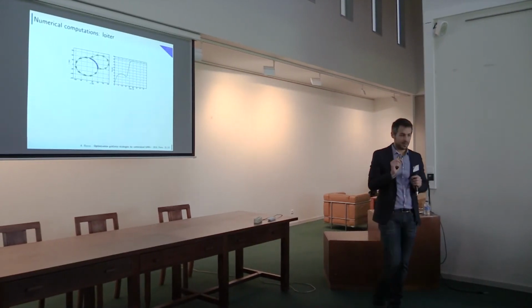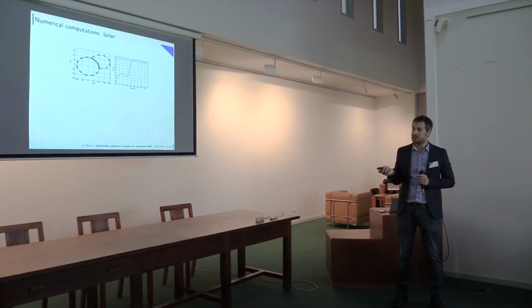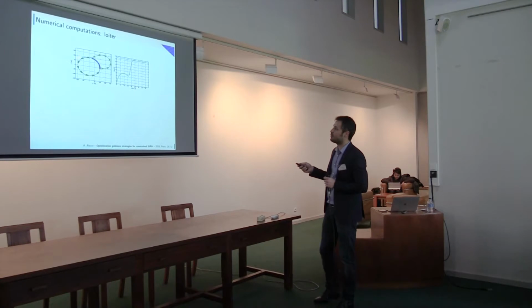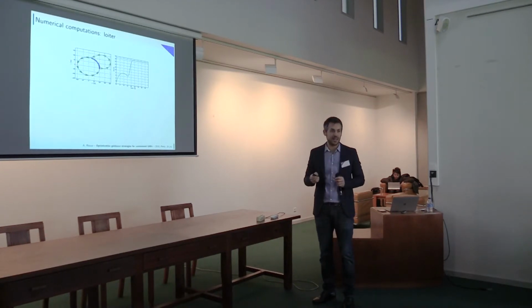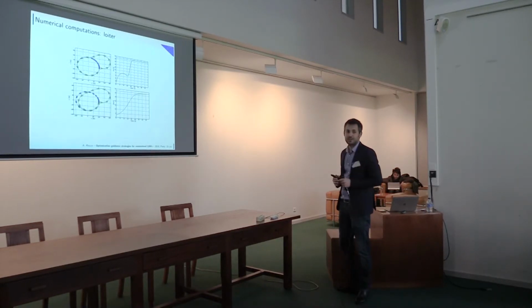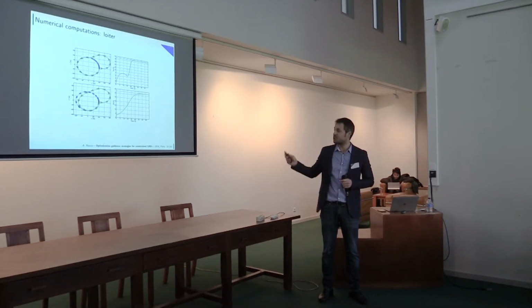And by changing some parameter of your cost function, what you can get is a path following behavior. So we don't care to be in a specific point of your loiter at a given time. But if we want a trajectory tracking approach, we change just one parameter of our framework, that is the R matrix in the optimal control problem.